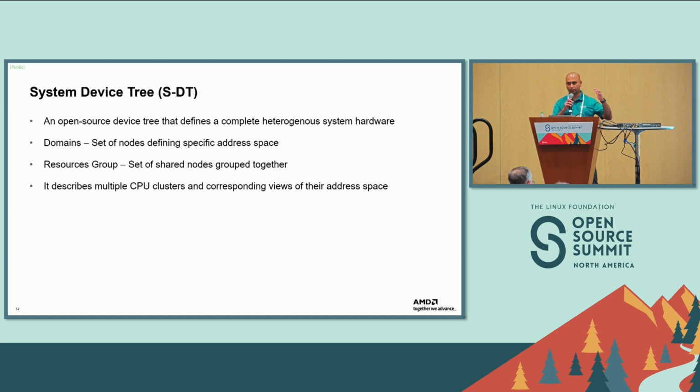For example, if you are building a device tree for a Cortex A processor, Core 0, you can build for Core 1, Core 2, etc. And each device tree can be used to build for a particular operating environment. For example, if you build a device tree for Cortex A Core 0, you can run Linux, and for Cortex R Core 0, you can run bare metal or RTOS.